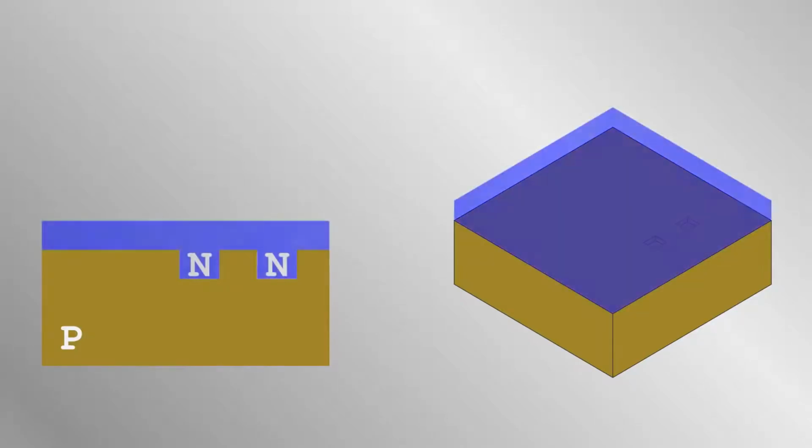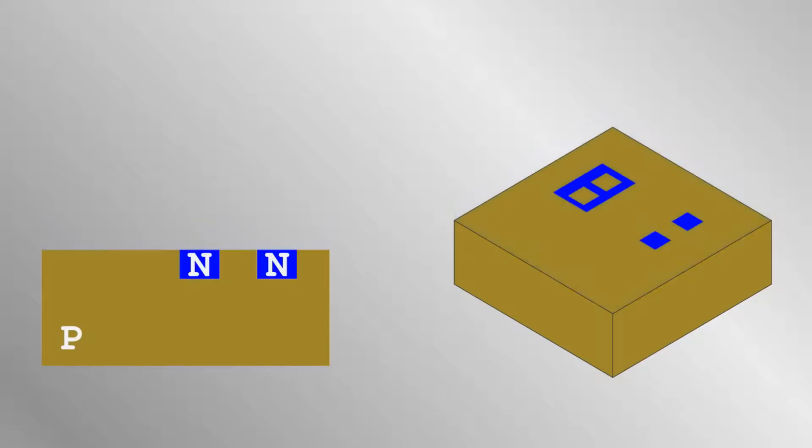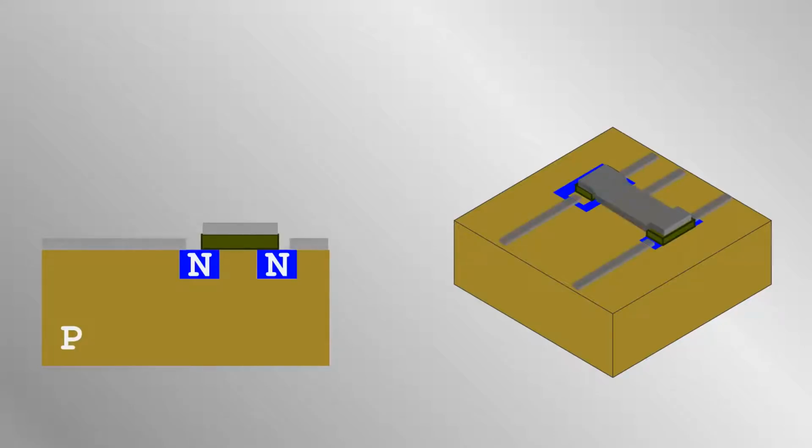The two techniques of deposition and etching used in conjunction mean that the N-type dopants for all the transistors on the die can be added simultaneously. Next, the silicon oxide is deposited and etched, and finally metal is deposited and etched away to leave metal channels on top of the die. These metal features form not just the conducting terminals of the transistors, but also the tracks equivalent to wires in a circuit, which connect the transistors as required.